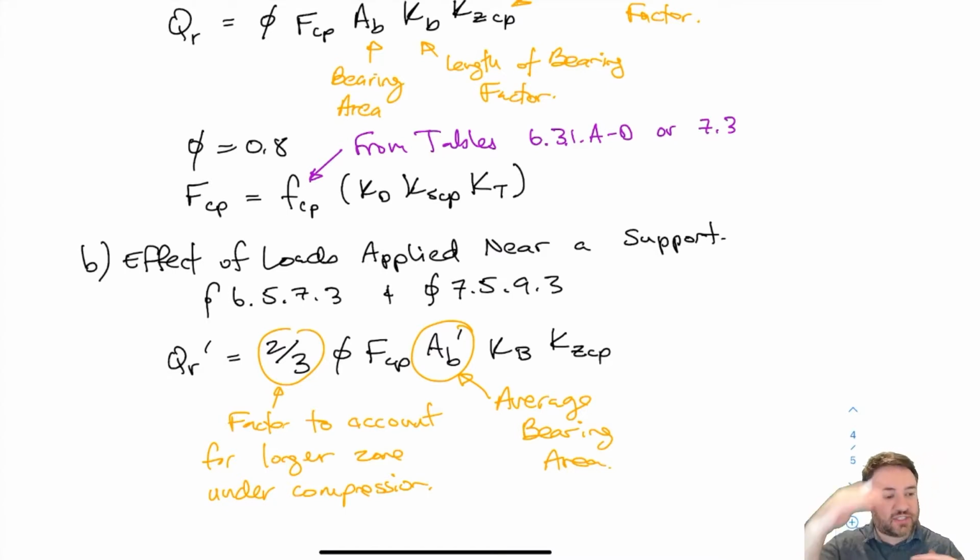So we have to have some way of accounting for the fact that the bearing surface is different on the top and bottom to come up with some kind of effective criteria. And basically the way that they do it is they take a straight average, and there is a limit to make sure that you can't make one really big to compensate for one being really, really small.